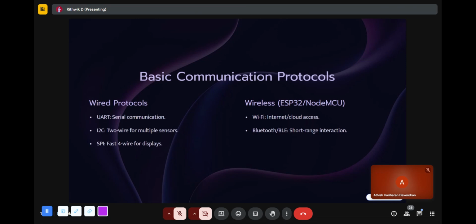And the third one is mainly used in Raspberry Pi. That is called SPI. SPI is basically complicated wiring. It will be having approximately 4 to 6 wires. And in the market, there are some converters available to change the connection of SPI to I2C so that we can connect sensors that are mainly designed for Raspberry Pi to ESPs and Arduino using just two wires. So that is the main advantage of those converters. You can just search for an SPI to I2C converter. It is cheaply available in the market for about 49 rupees or something.